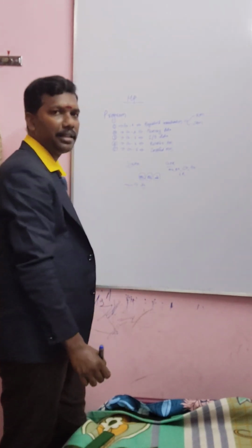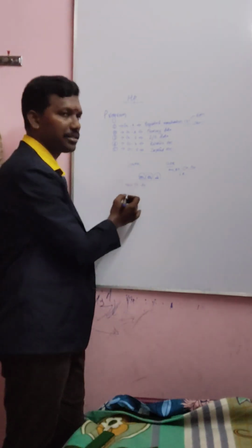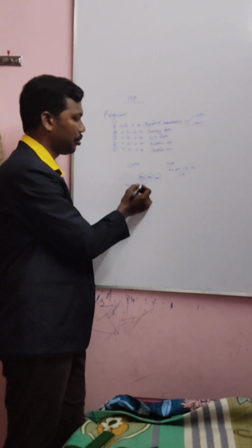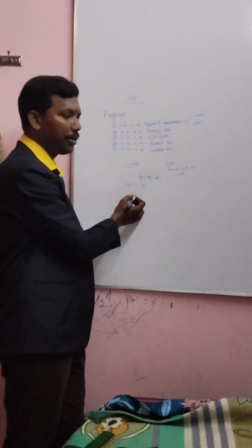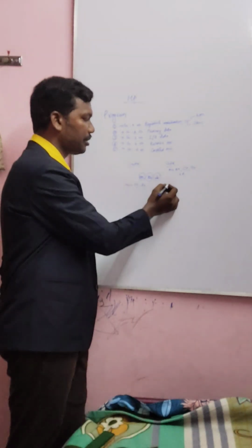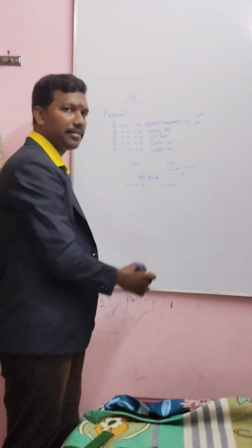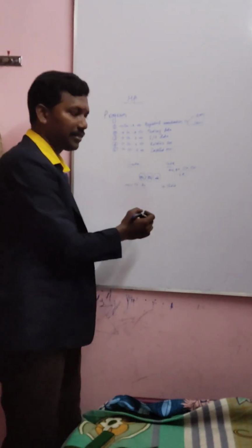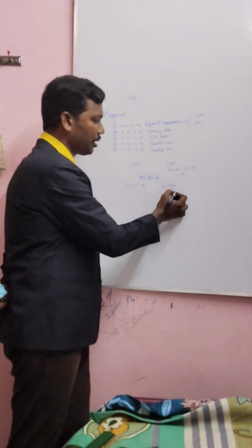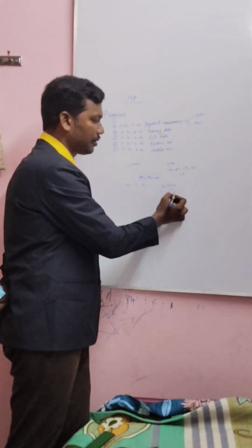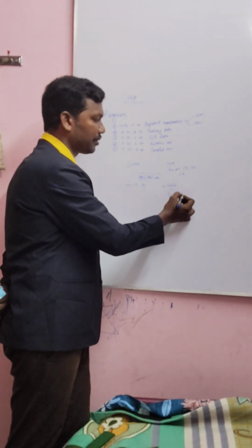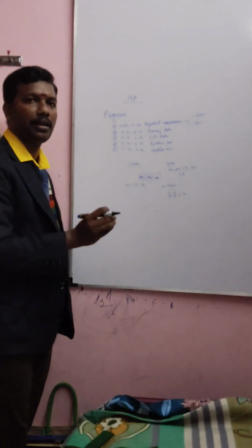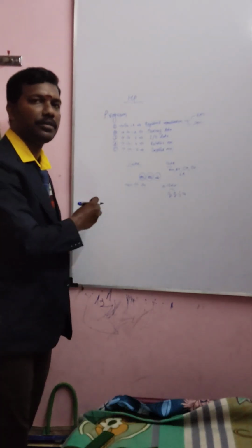So what does it mean? Two registers will be taken: C register with the low, D register with the low. Each and every register is a 16-bit register, and in the 16-bit registers we can use it as a lower and higher. So lower contains 8 bits, and higher contains the other 8 bits. So this instruction represents one 8-bit data moving from one register to another register.